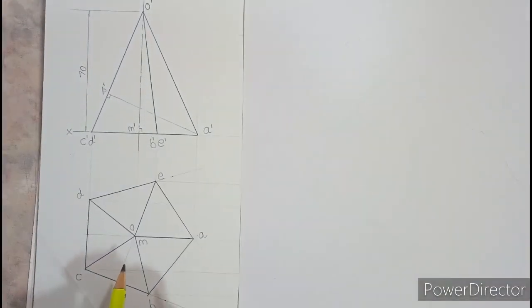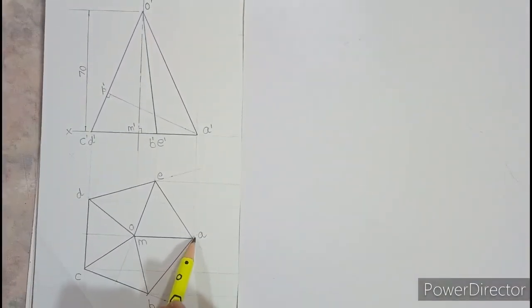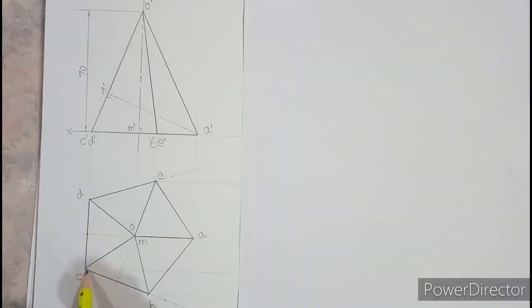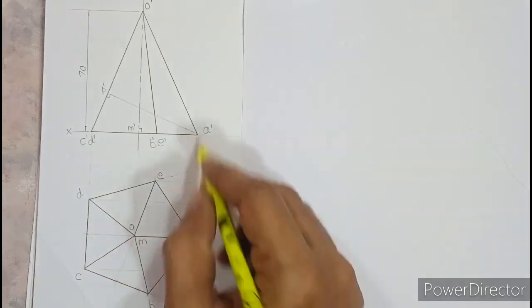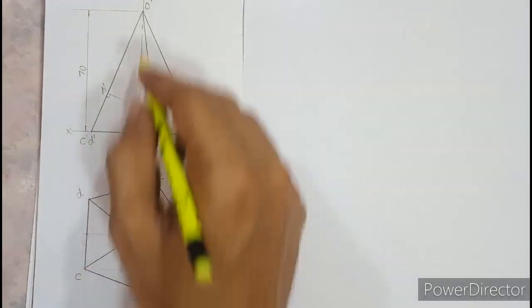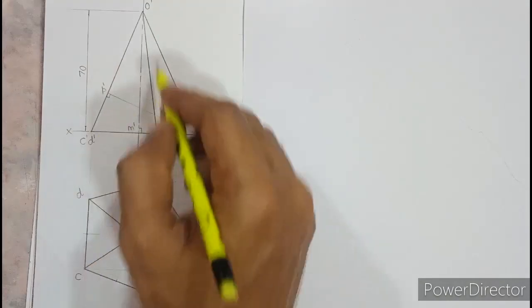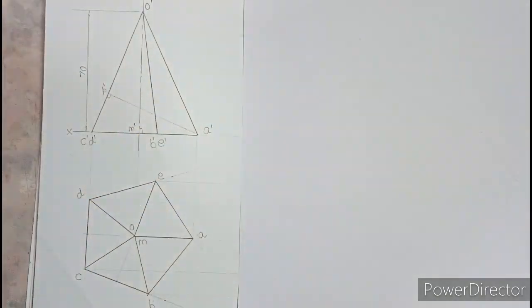As it is a corner resting question, we need the corner on the right side. So to start with, the base is on the left. Draw a line of 40 mm, draw 108 degrees, mark 40 on each side and complete the pentagon. Also locate O and M and draw the 5 slant edges dark. In the next view, by projecting A, E, B, C, D, O, M, you can get a triangle, draw it dark and mark the axis as 70 mm.